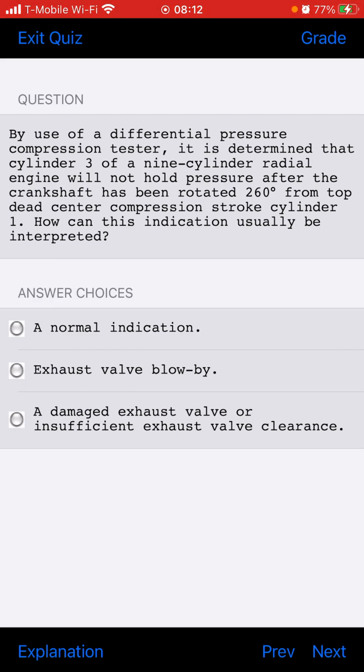The actual power delivered to the propeller of an aircraft engine is called brake horsepower. The volume of a cylinder equals 70 cubic inches when the piston is at bottom center, and when the piston is at top of the cylinder the volume equals 10 cubic inches. What is the compression ratio? 7:1.